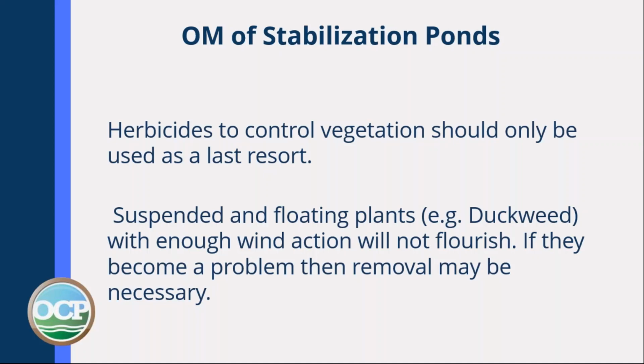Suspended and floating plants like duckweed, with enough wind action, will not flourish, but they can become a problem. If they do, removal may be necessary. The only way to get rid of duckweed is pretty much to scrape it off the top and dig and throw it out of the lagoon.